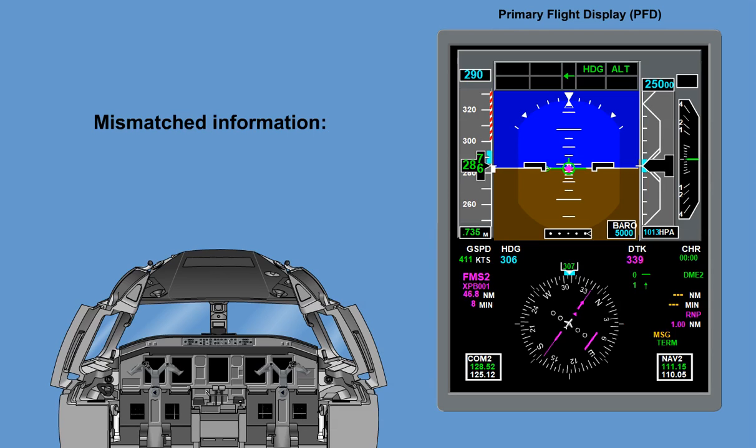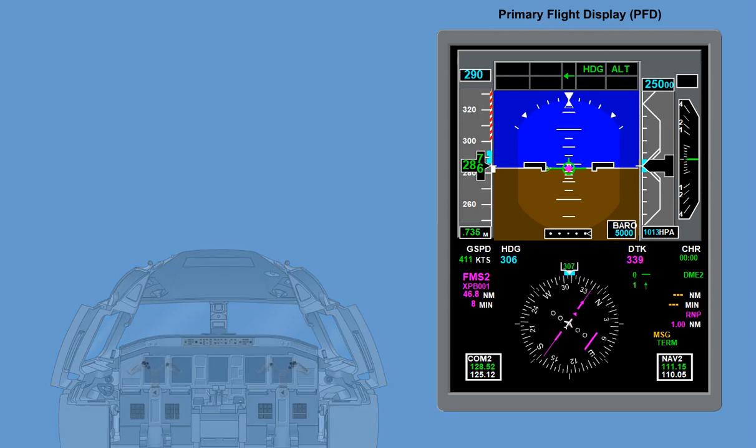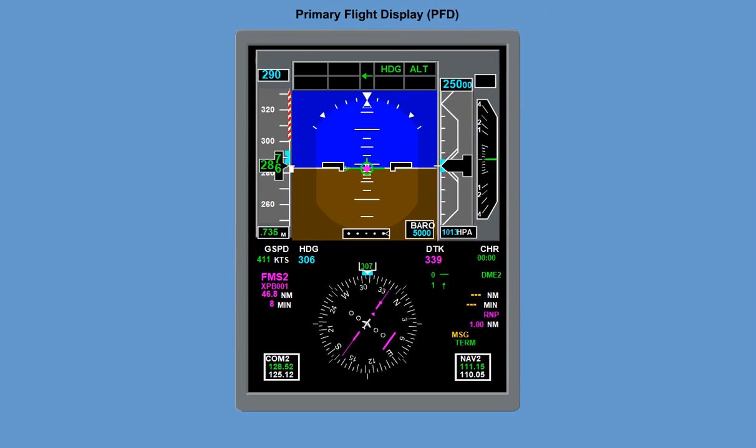For example, a CAS flag is displayed whenever airspeed miscompare is detected, or a LOC flag whenever a localizer miscompare is detected. Here you see an overview of all flags which could appear in case of a PFD miscompare.